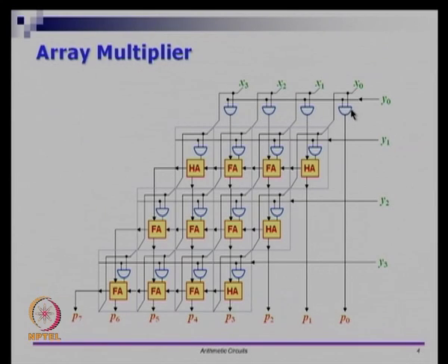So, that is P1. You continue doing this for each and every step. The very first stage is just AND gates. In every partial product stage, if you put this circuit here, half adder, full adder, and half adder. So, I guess this must also be a full adder. That is a mistake here. Okay, this is not a full adder, it is only a half adder. So, this is fine. If you do the circuit here, it is taking partial products coming from two levels, adding them together, generating the sum, and that sum can be added with the next partial product array, that will give you the next sum and so on.